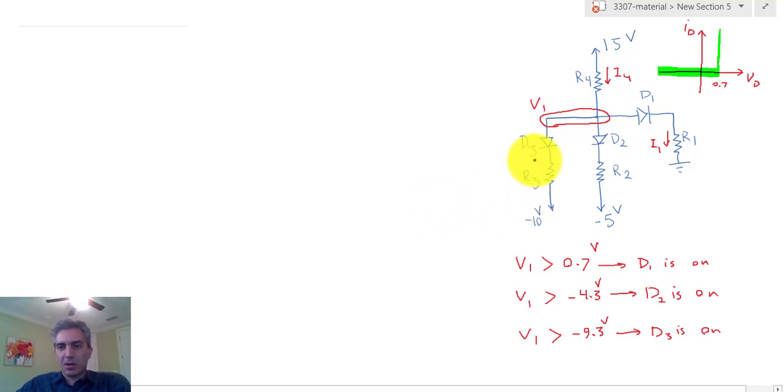So at least D3 is on at all times. And then if D2 is on, D3 is definitely on. And if D1 is on, D2 and D3 are on. These are all the conditions that you can quickly conclude based on the circuit and what we have down here. So with that, now I can start writing conditions for any of these situations to happen one by one. And in order to do that, I'm going to actually put V1 right at the edge when this happens. Basically the diode is going to turn on, and write equations that relate these resistors to each other.